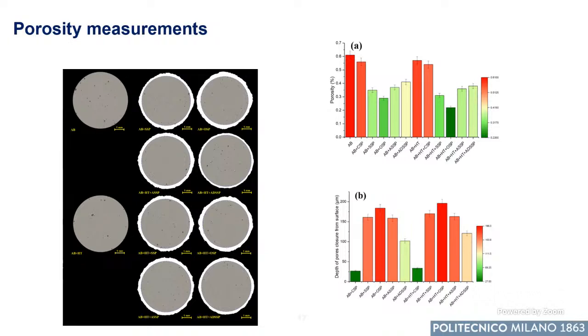We have seen that from this point of view, conventional shot peening is not able to go so deep, while if we are considering the ascending descending shot peening or also severe shot peening, the effect is much more remarkable. And also in this case, the application of heat treatment is not important, at least for this kind of analysis.